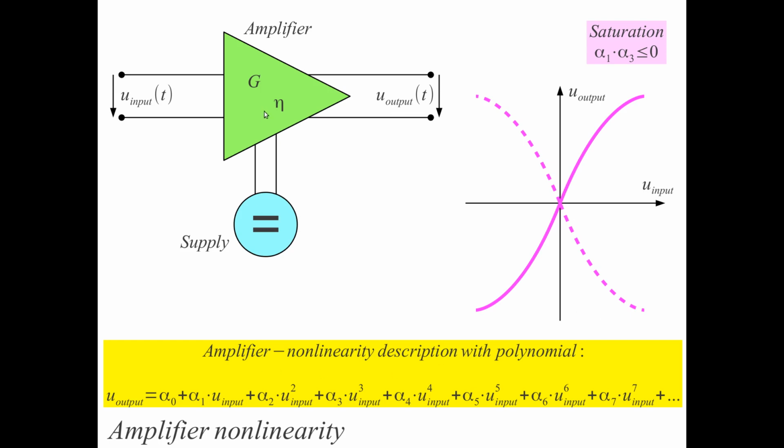And for such an amplifier that has nonlinearity but has no memory effects inside, no resonators, no tuned circuits, so no group delay in the amplifier, we can express the amplifier response, of course in voltage, not in power, because power will not tell you anything about distortion in detail. With the input voltage as a function of time in the time domain, we can calculate the output voltage at any particular time. If the amplifier has no memory, we get an immediate result out of this function, and we can rewrite the amplifier response as a polynomial that has a DC term here, that has a linear gain with alpha 1, that has square distortion, cubic distortion. We actually see cubic distortion over here. And it also has higher order distortions up to infinity here. The polynomial may have an infinite number of terms to actually describe our amplifier.